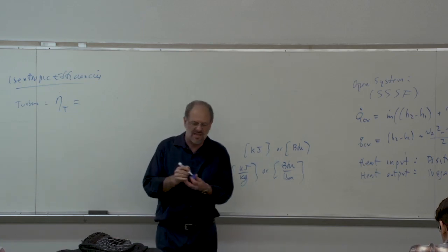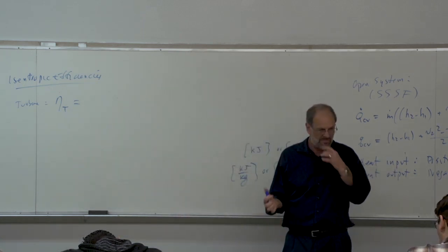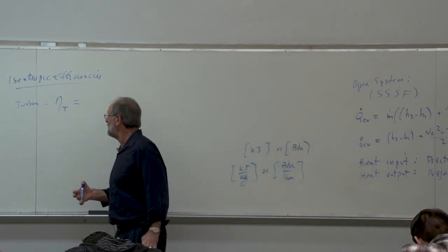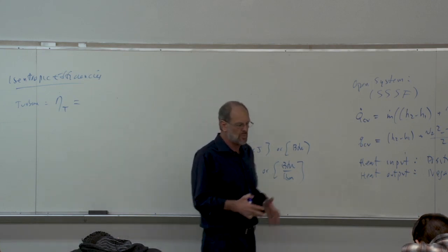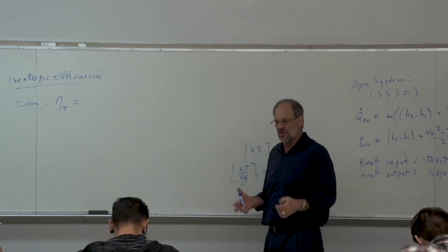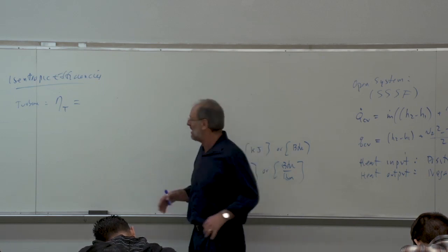By the way, this is data that will always be given to you. When you buy one of these big devices, the company that's manufactured it is going to have tested it out. They will tell you exactly what the efficiency is over a wide range of operating conditions, a wide range of flow rates, a wide range of pressure changes or temperature changes. So you'll have a performance characteristic curve, which we might just call a map, because that's what we call it.